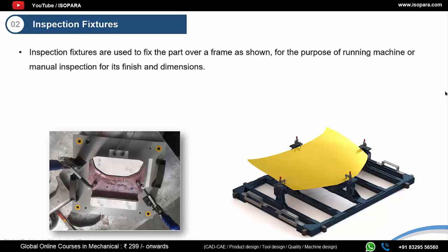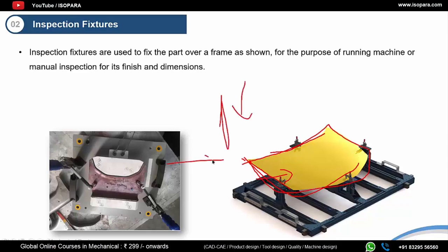Like I said, everything is mass produced. They are just a component and component being produced one after another. Let's consider this hood. This is a hood of the car, or the frame, or the sheet for the hood of the car. It will be welded onto the body chassis or the frame of the car body. This is done by cutting it from the sheet metal and then forming it in the required shape. The press would just go up and down, and the sheet will be unrolled.